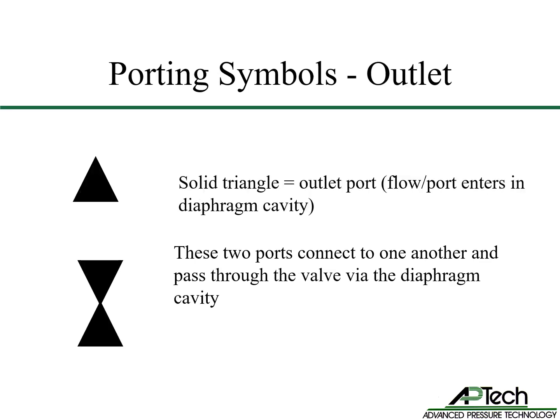A solid triangle is an outlet port. This port is downstream the seat. Two solid triangles is two common ports downstream the seat, passing through the diaphragm cavity.